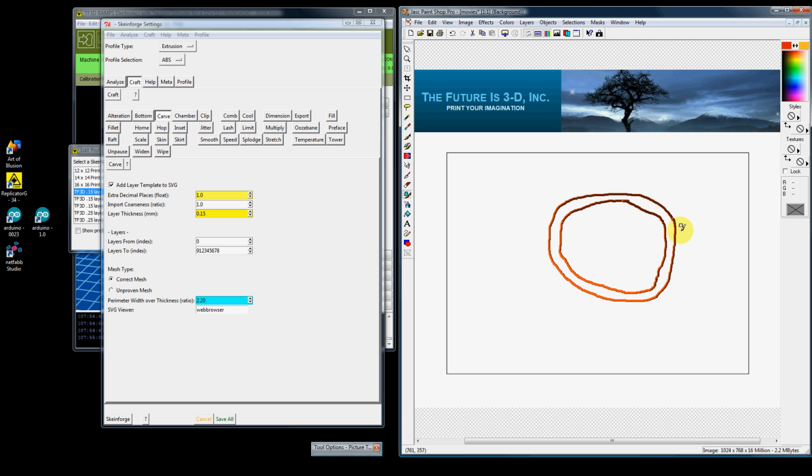So if you want to get that closer, you want to lower this number. Now we'll go ahead and lower this number to the absolute lowest. You can type in lower numbers, you can type 1.2, 1.1, but the system stops you here, and we'll just do that. So 0.14 has brought this closer. So now you're riding right along the next object, right on top of it.